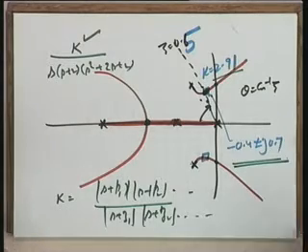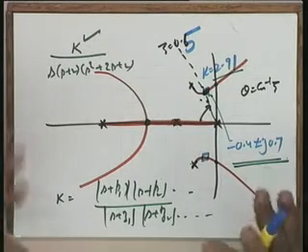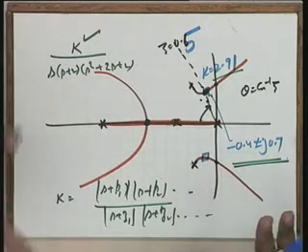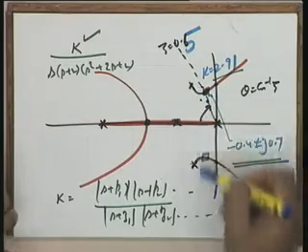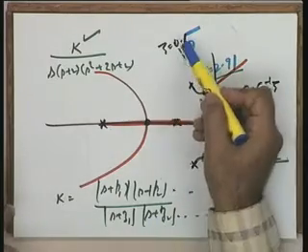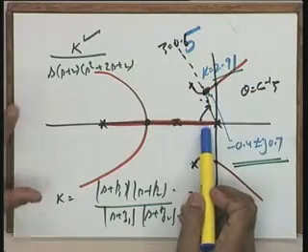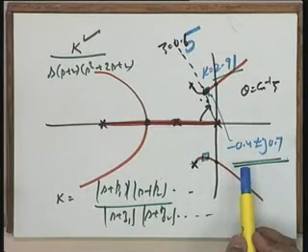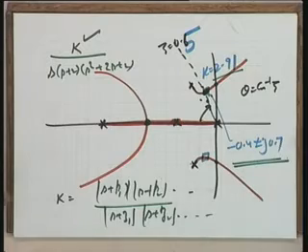Now, as I told you, it is a comprehensive example; it has all the ingredients which are needed in a root locus design. So, do not worry about the complexity. What are the other things? The other things are finding the other two closed loop poles. After all, it is a fourth order system. You have found the two poles, and you know that zeta equal to 0.5 has a meaning only when the other two closed loop poles are insignificant. That is, these two poles are dominant in nature, and for that you require the location of the other two closed loop poles. How to determine the other two closed loop poles?